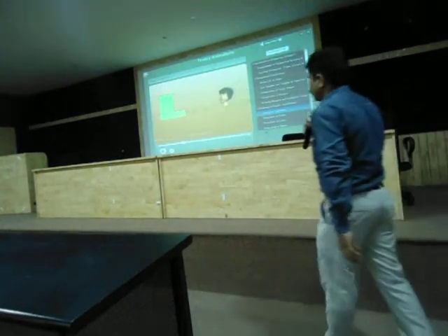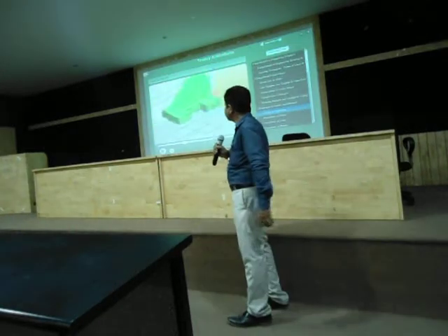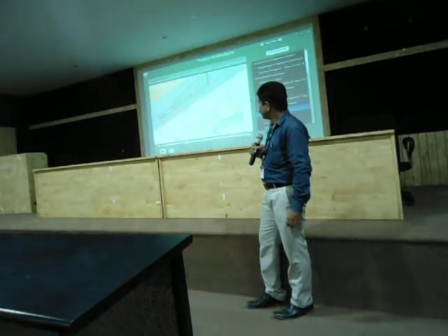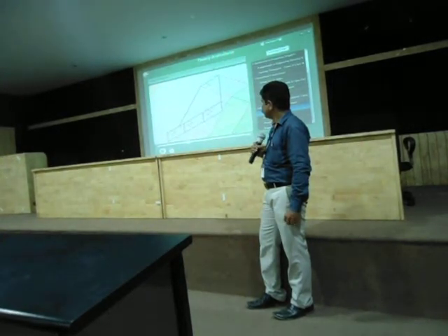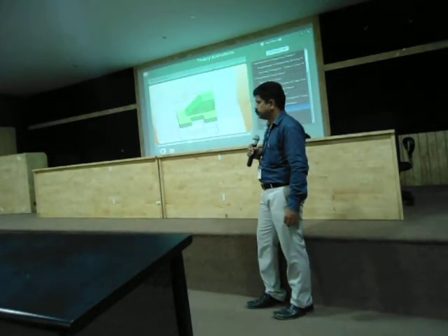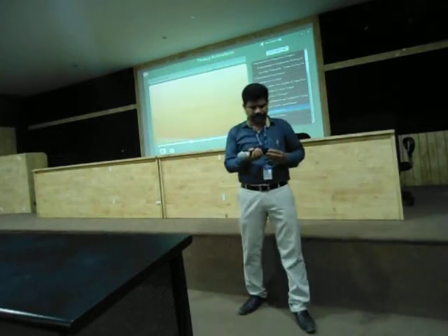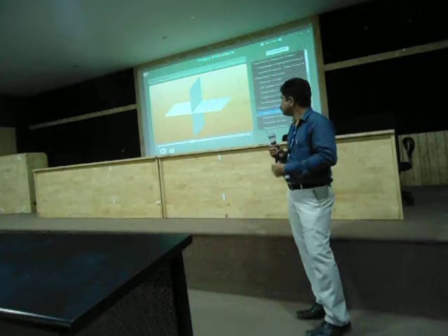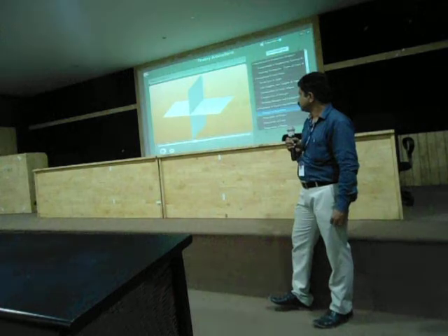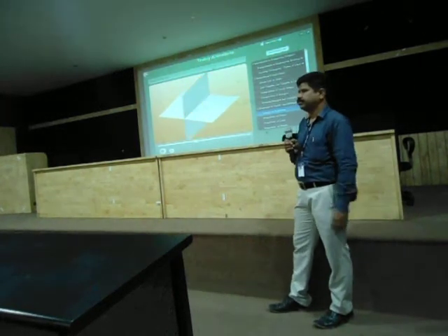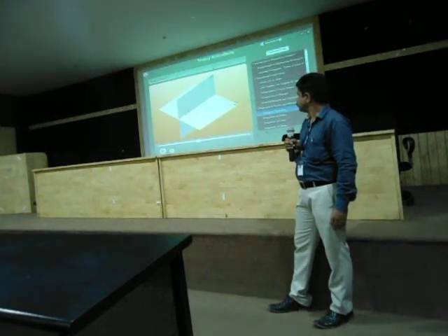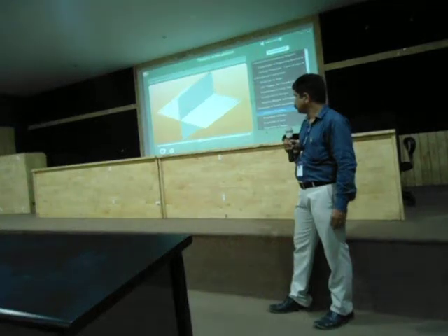And the distance between the object and the viewer. The projectors are perpendicular to the plane of projection. This type is known as orthogonal projection, which is prominently used in engineering drawing as it shows true size, proportions and shape of the objects. Planes of projection are mutually perpendicular planes known as principal or reference planes. One of them is the vertical plane VP and another one is the horizontal plane HP. The intersecting line XY is the reference line.